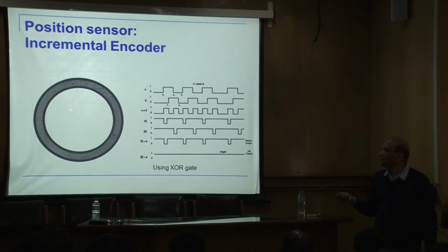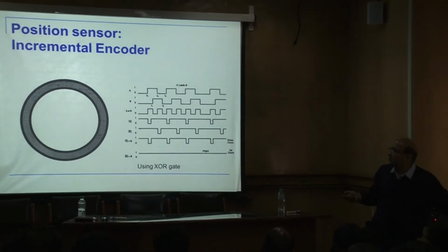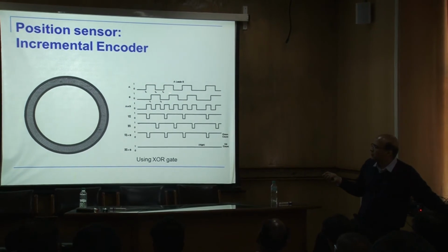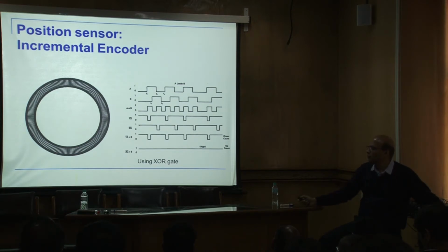Okay. So we have a DC motor. At the back of the DC motor, there's an encoder. This is an industrial motor, and we can read the signal using a microcontroller input channel. From one channel, you can take the input and simply check when it is high and when it is low. Okay. Now, depending on how many highs and lows are there, that is the angle by which it is moved. Okay. So if you want to control the motor, move it to some position, you know exactly how many pulses should be there. So it can count those many pulses and stop when it reaches. Okay. So this is one experiment we have today in the afternoon, where you have to control the position of a motor by using an encoder with a microcontroller.